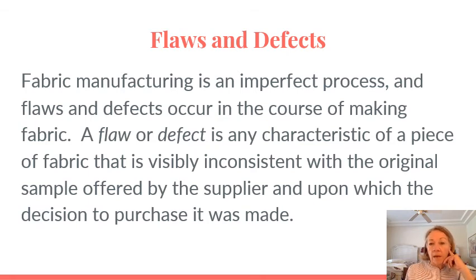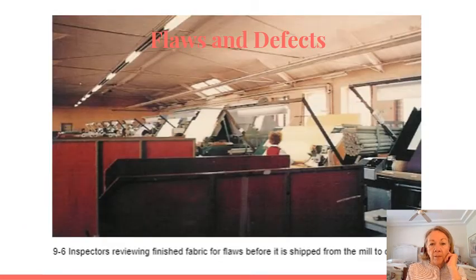They can't be sold as perfectly quality material. And I think we talked with this class, or it'll come up later on in this class, that one flaw for every 10 yards is what's acceptable in the industry, but the edge of the fabric should be marked with a yarn showing you where that flaw is, so that it's not going to be a surprise to you.